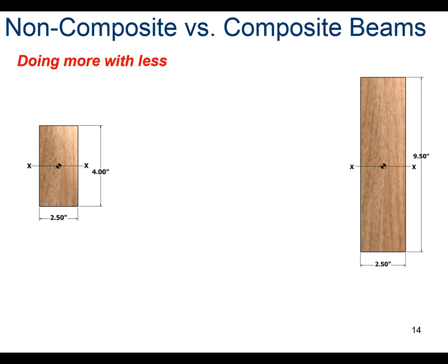Using the formula provided earlier, you could easily calculate what the moment of inertia will be for both of those two beams. The smaller one has a moment of inertia of about 13, while the larger one is 178. The larger beam would be about 13.4 times stiffer than the smaller. If you were an engineer in charge of building some kind of support structure to hold up a heavy load, it would be logical to think that the beam on the right would be a good choice because of its higher moment of inertia. It will deflect less than the beam on the left.